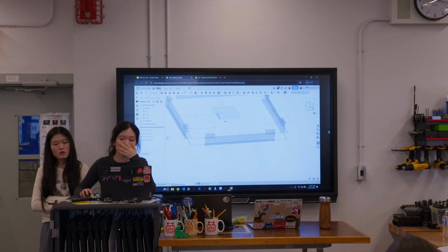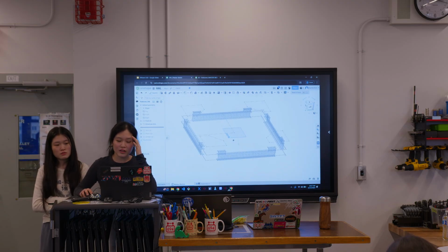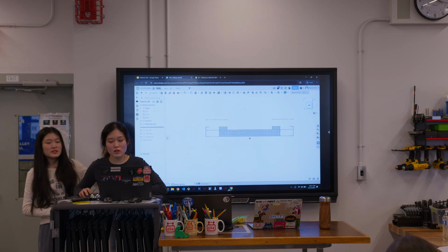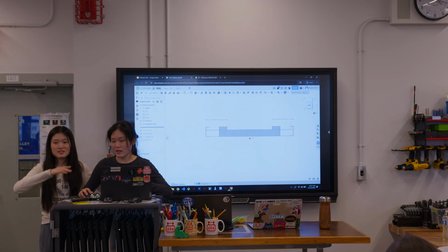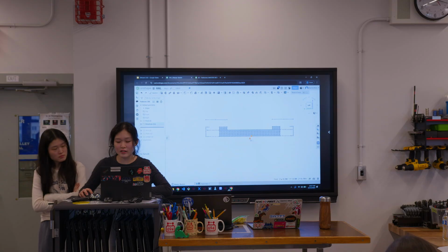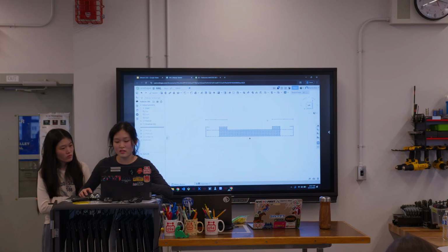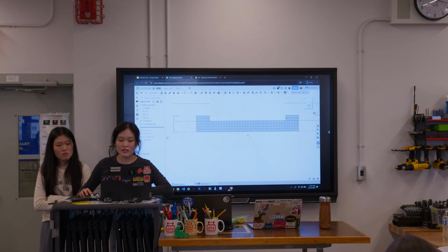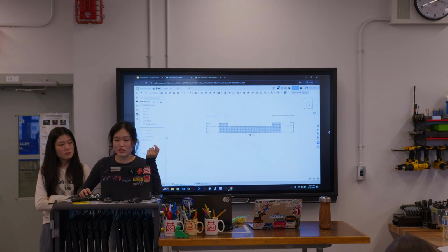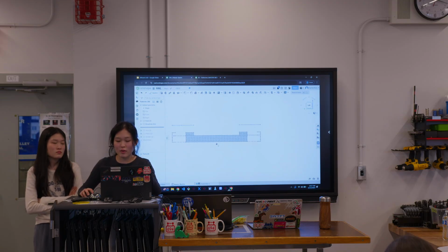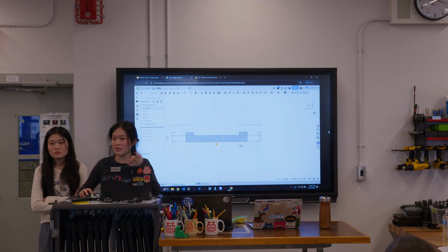So we're also very conscious about where we place our sketches and where we start. Basically, the origin represents the ground. So you don't want the tubing to be directly touching the origin because that's not the ground. This also makes it easier because let's say someone's master sketching an intake, and the origin represents the ground, everyone can universally say.